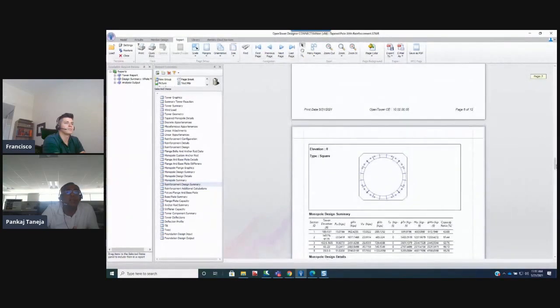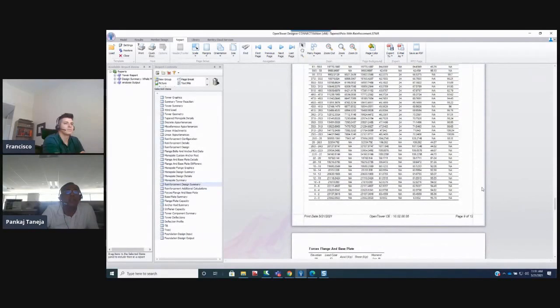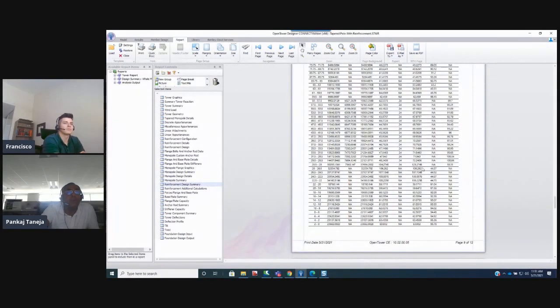Here you can see that we provide the picture so the user knows what we are doing, and now you can see all this stuff, the reports and everything. I have put in the reinforcement, but you can still see that it's failing with 100.86. It's very close. In the industry, because I have put 105% as my max, that's why this is passing too.